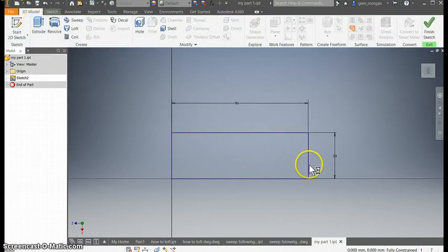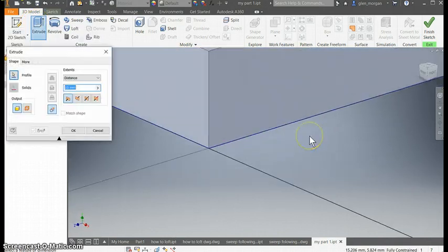Now, this drawing has turned blue. You might have noticed that. That's because it's fully constrained. It starts from the point 0, 0, 0, and it has 2 dimensions on it, which means it's constrained. Once a drawing is constrained, it's considered a bounded area, so therefore we can extrude it. So if we click on this extrude button now, it will throw us back into 3D.